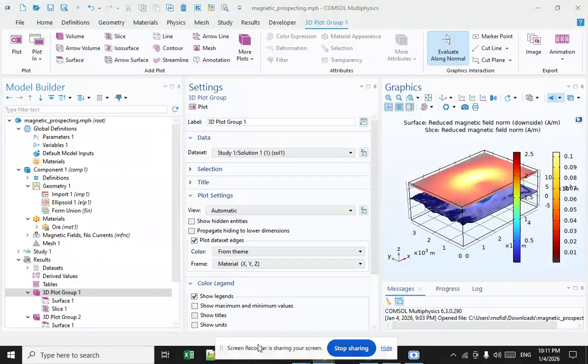Extraction. Lower grade sources of iron ore generally require beneficiation using techniques like crushing, milling, gravity or heavy media separation, screening, and silica froth flotation to improve the concentration of the ore and remove impurities. The results, high quality fine ore powders, are known as fines. Magnetite is magnetic and hence easily separated from the gangue minerals and capable of producing a high-grade concentrate with very low levels of impurities.